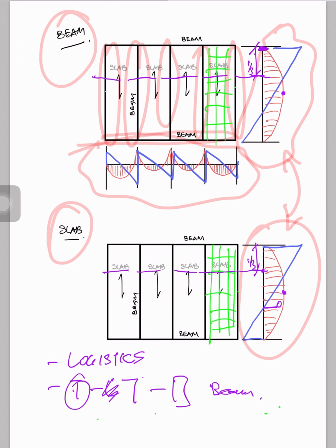Because if it's T-beam or L-shaped beam, it's going to take up a chunk of the slab in terms of the design analysis, and so inducing the construction joint for the slab and beam, you would have to have it coincide. Unlike a rectangular beam, where you may have the construction joint slightly different from where the slab construction joint is, depending on site. But however, it is always best practice to have the CJ coincide with the beam and slab.